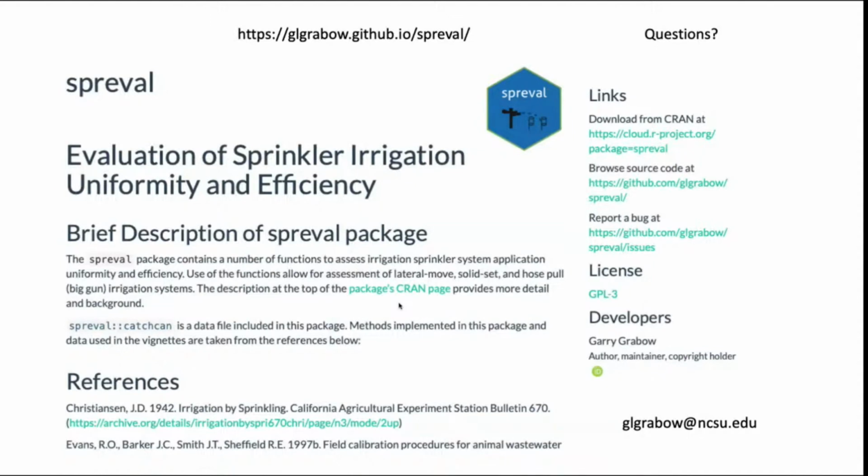It has been done. I have done a number of research experiments on subsurface drip irrigation, and I'm assuming that's what you mean, below the ground level, for agricultural crops like cotton and corn and soybeans and whatnot. It has been done in turf. I don't have direct experience with it. I know it's been done. There you would want to be very careful about filtering your water, especially if you took it from a pond or even groundwater and it wasn't from municipal supply.